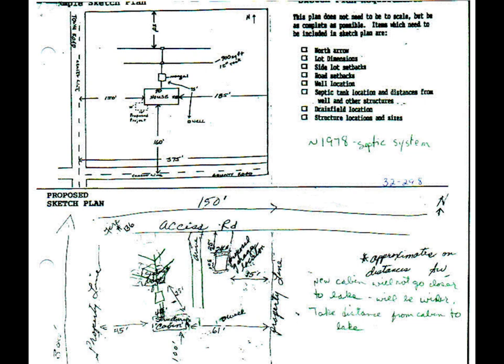I then educated myself in septic field soil requirements. I learned the words and what we were looking for, such as redoximorphic features, redox. Again, these show where groundwater has historically come through the soil, leaving horizontal iron trace marks.